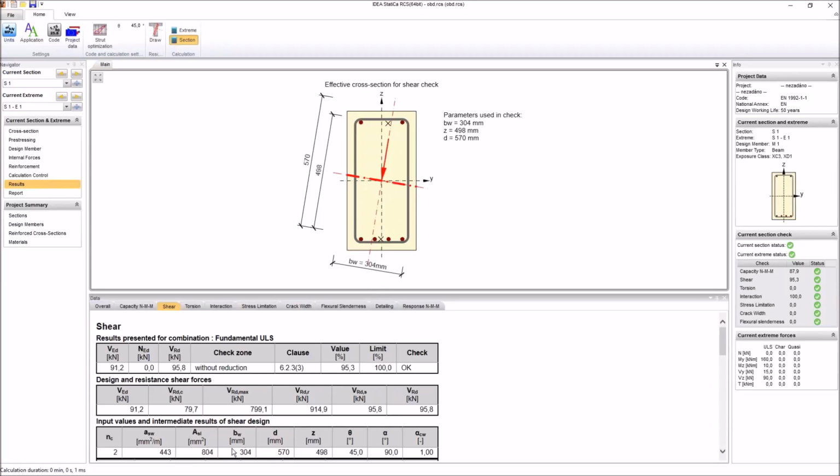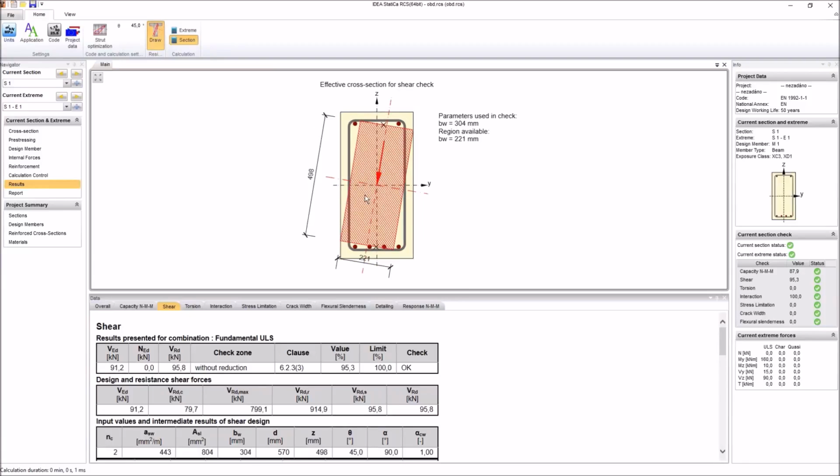We use this 300 because, as I mentioned, we do not want to reduce it too much, but you can draw it, you can see what is the result if the strut can appear in the cross section. Sometimes if it's, for example, a very slender T-section, a very deep T-section or I-section, then the strut can go even outside of the cross-section, which you can check. And in case that you are not happy about the geometry, you can easily change it in the user-defined values.